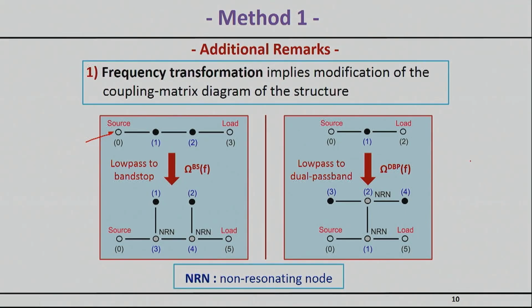When you do the frequency transformation, that actually loses its meaning, because the true coupling topology that you will physically implement will not actually look something like this, right? This is essentially a mathematical technique that allows you to get the real response from a synthesized response, but the real filter that you will build will not look like that. In fact, the real filter that you will build, if let's say we are transforming things from low pass to band stop, it will actually look something that you see down there.